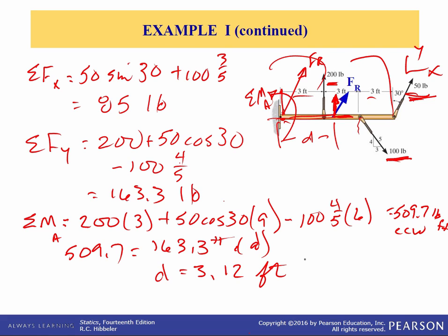So what I've done is I've taken all those forces and reduced them to one single force, F sub r, acting at some distance away from point A. In this case, the resultant moment is 0. We just replaced everything with one single force acting at some point. Makes analysis so much easier when you can do this.